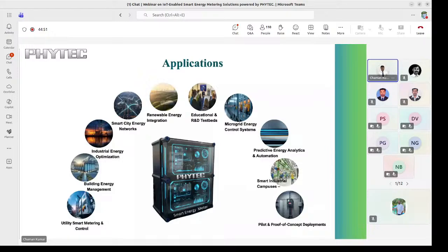So now once we understand the smart energy meter, we will understand what the smart energy meter system is, and what the whole architecture is. Then now we have to understand the communication protocols, meaning how many communication protocols there are. If you see the communication technologies, one is the wireless star network, another is the RF mesh network, and PLC. In the wireless star network, we have 3G and 4G.